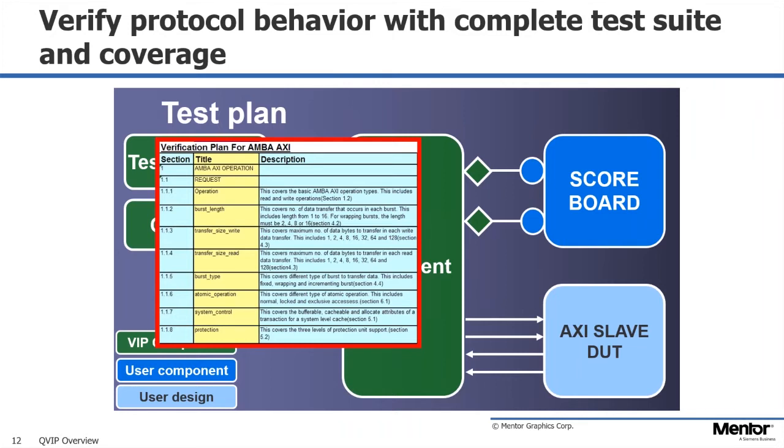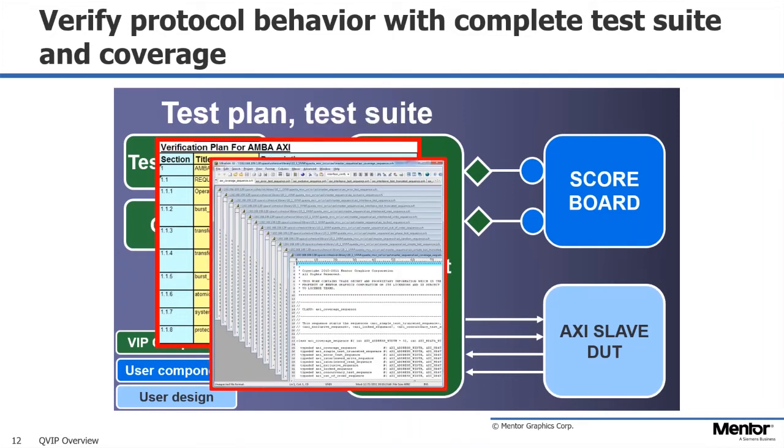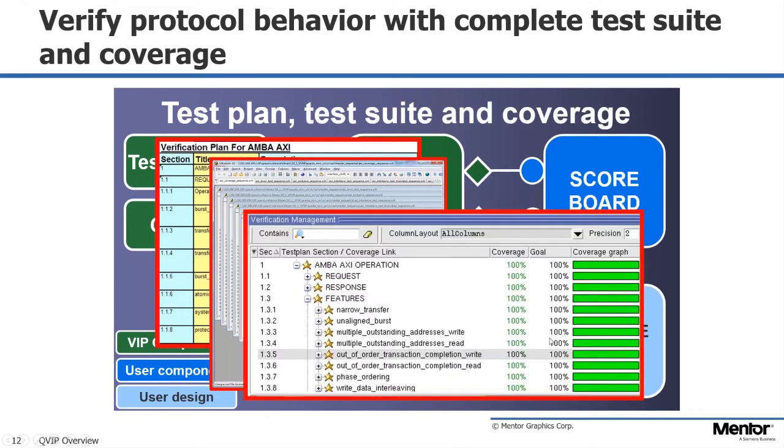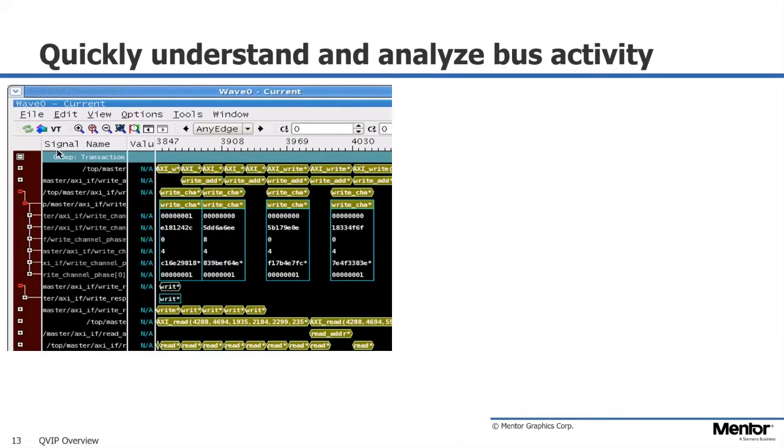So as I said, we start with that test plan. From that test plan, we build out a full set of sequences. Those sequences, we give you the API to say, I want to send this type of sequence. As soon as you include that piece of IP in your test bench, you're given full documentation on that sequence. This is an example of transaction level debugging.